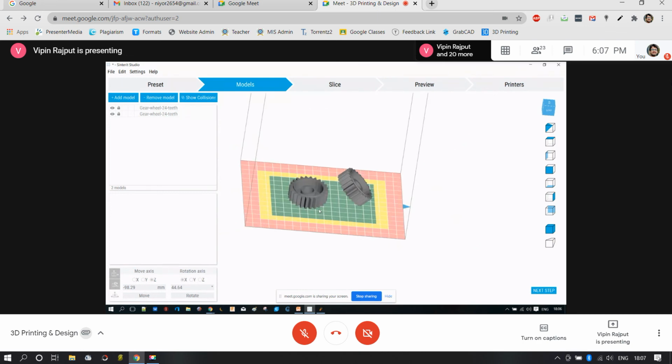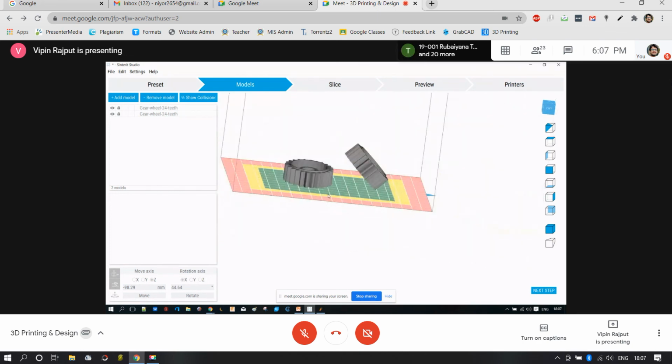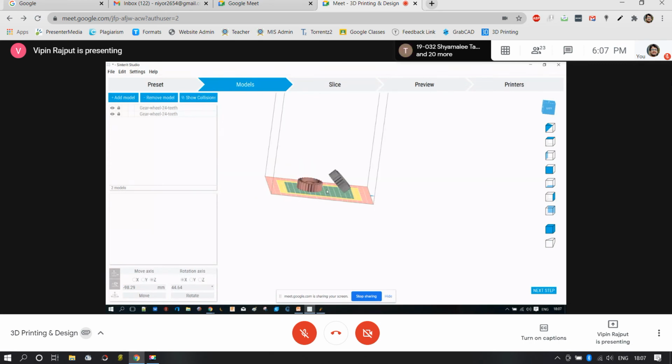See, a heated bed is not available in the machine. The particular area where the part is getting formed, just above it, you do have heaters and pyrometers, which are responsible for providing heat to the topmost layer. The bed at the bottom of the powder is not a heated bed, so over the top, you can experience some amount of heat.